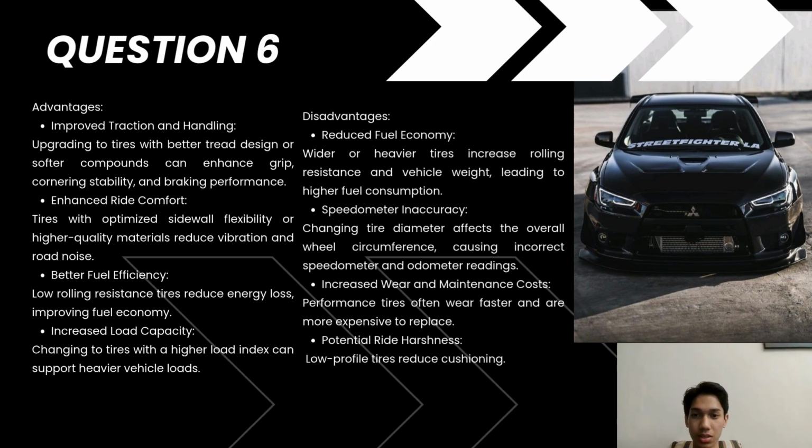Next would be enhanced ride comfort. The tires with optimized sidewall flexibility or higher quality materials reduce vibration and road noise. Next would be better fuel efficiency. The low rolling resistance tires reduce energy loss, which would improve fuel economy. Next is increased load capacity. Changing to tires with a higher load index can support heavier vehicle loads.